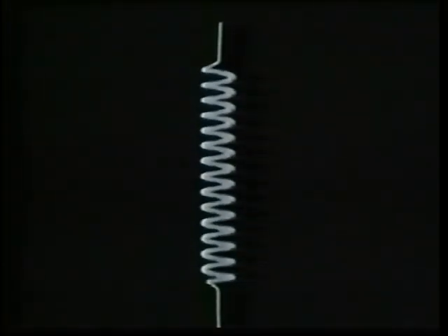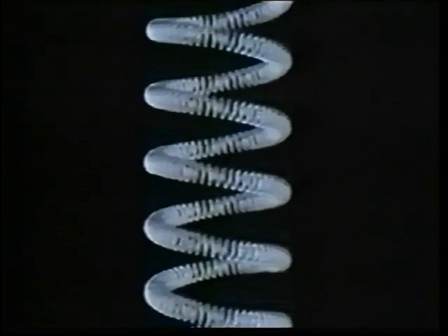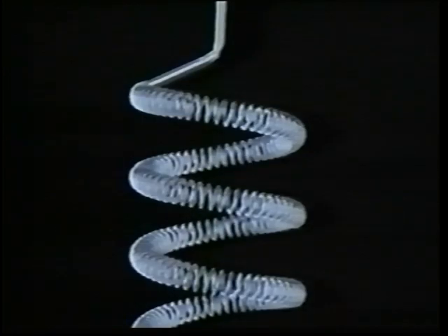Filaments are manufactured in a variety of shapes, depending on the end use of the lamp. Usually it's either a coil or a coiled coil. Coiling improves efficiency by helping retain heat in the filament. If a coil stays hot, it needs less electricity to keep glowing.